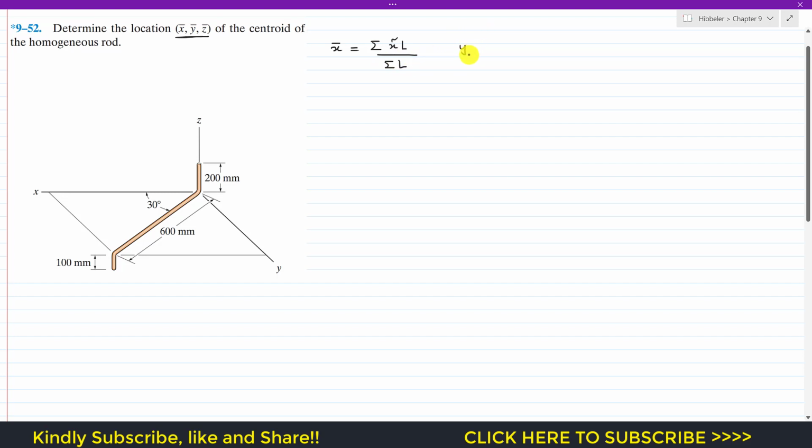Similarly, y bar will be equal to the summation of y tilde times L divided by the summation of length, and similarly z bar is equal to the summation of z tilde times L divided by the total length of that rod.